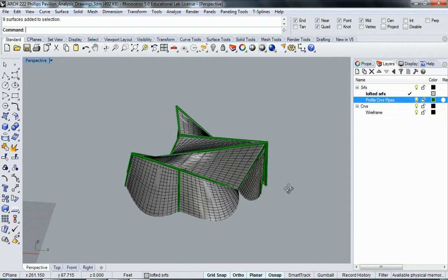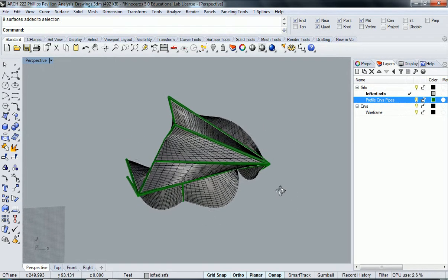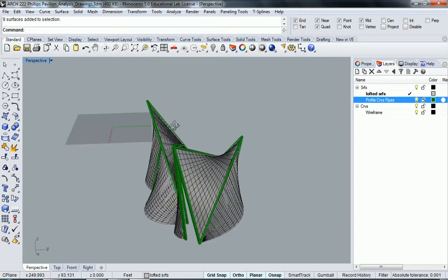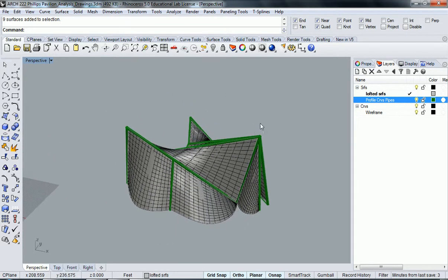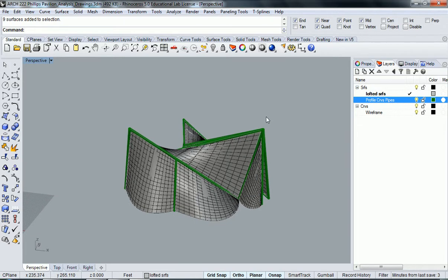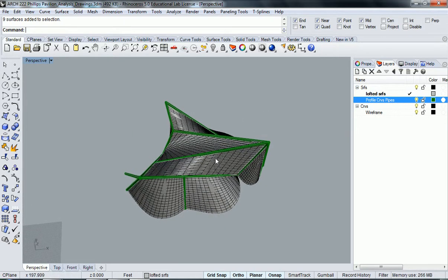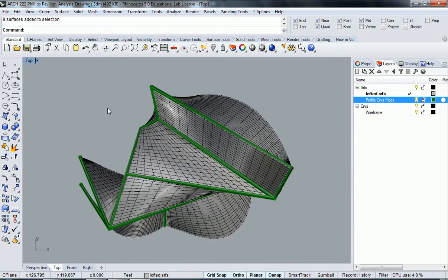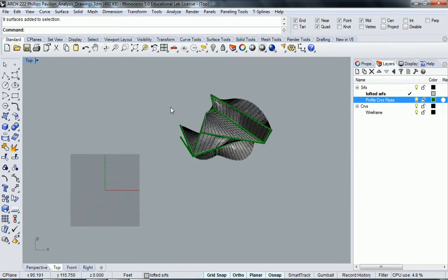So now I have all my layers back on, and let's get ready to produce our first drawing here. We have one thing we need to do, or you know what? We're actually good. Let's actually make that first drawing. So I'm going to go into top view. And if your model isn't already, move it away from the 0, 0, 0 point, because that's where your make 2D is going to show up. And you don't want your drawing to show up underneath your model.